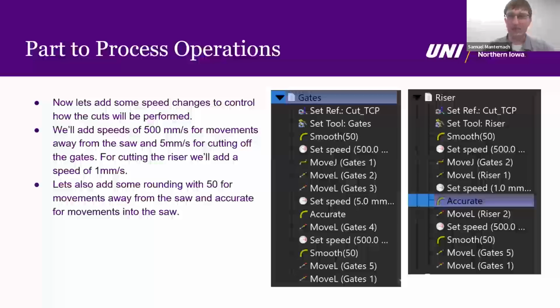Beyond this further, for a lot of higher volume or different geometry of parts, there are a variety of other cutting options you can use inside of a robotic cell, depending on what material you're working with. There's also been great success with using cold saws for this operation, which is a very nice, consistent way.